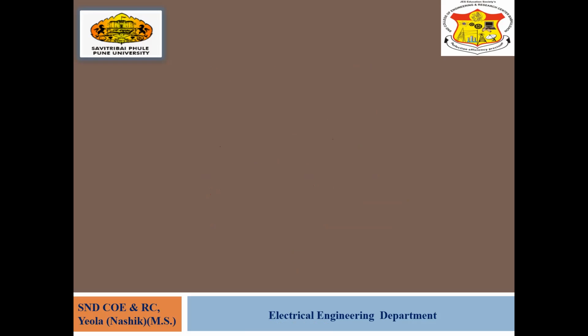So in this lecture, we will see the topic called the cascade transformer. Why cascade? You are well acquainted with the term cascading, connecting one or two units together. That means the output of the first is given as the input to the second. So why is it essential to go for the cascading of transformers? Because we can't build a transformer above 700 kV in a single piece. It is not economical and the size is very huge. So considering this point, we are going for the cascading of transformers.